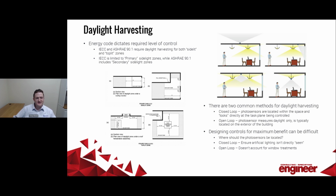Wanted to take a moment to talk directly about daylight harvesting, because it can be really tricky, and it's probably one of those fun code lighting control things that can be tough for you. So both ICC and ASHRAE have defined daylight zones now. 90.1 does have secondary daylight zones. I did just look into 2021. IECC does add secondary side lit zones as well.